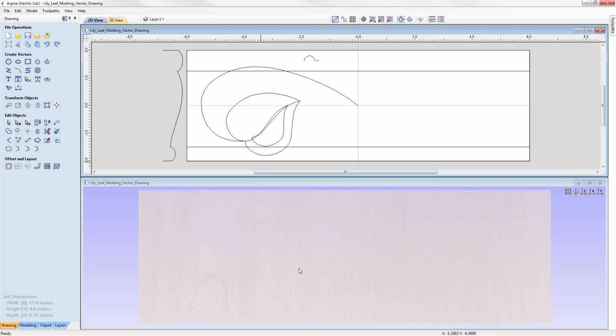Now, if you watched the previous tutorial to this example, you'll know that when we created these vectors, we created them in a way that uses specific modelling tools. So to create the base shape, we're going to look at using this vector here with this vector here, and we're going to use the 2-rail sweep tool. So these will be our 2 rails, in which case we're going to sweep this cross section in between the 2 rails to create the base moulding. So let's go and create that shape.